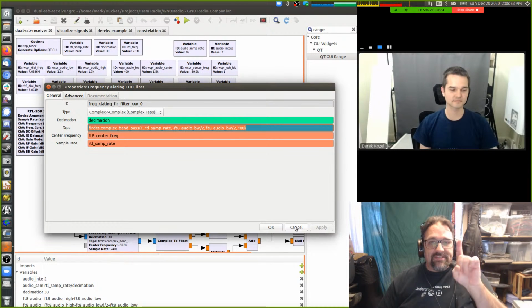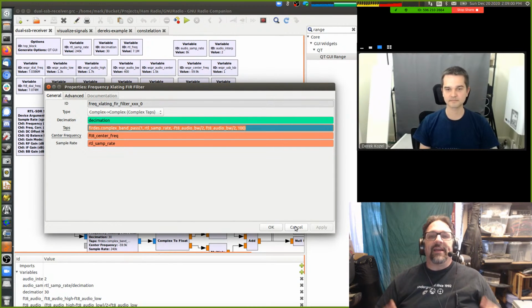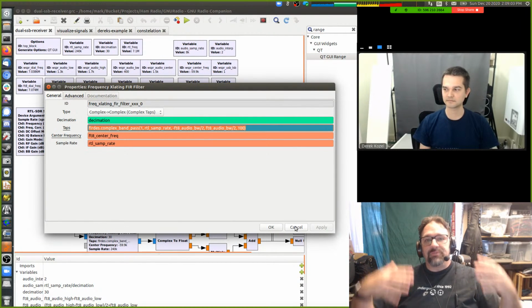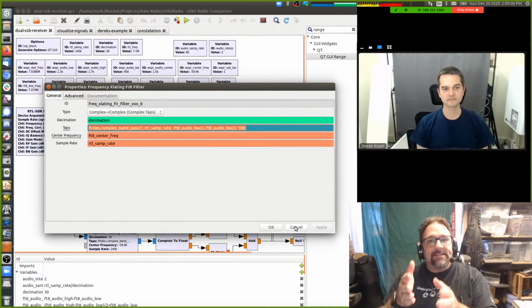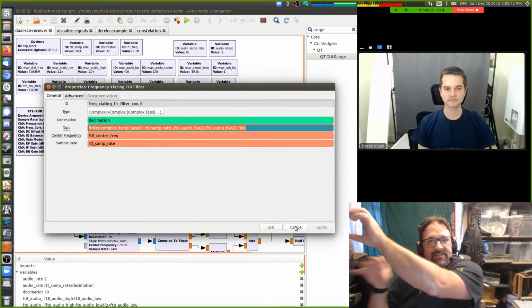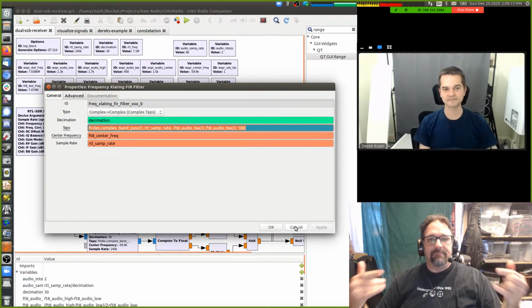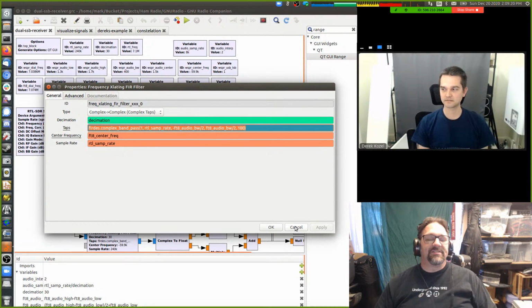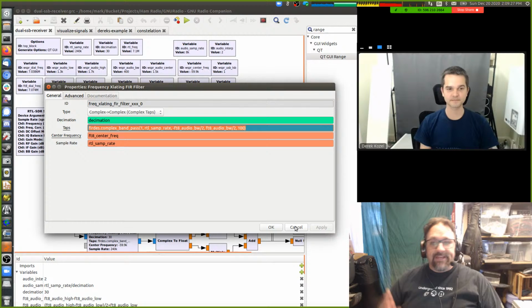So I'm now using a single instruction cycle to operate on 8 different values, 4 different multiplications. Again, it's a way of optimizing things when you've got a whole lot of multiplications that you need to do, and each one of those multiplications is independent. This value times this value, this times this. You don't need to do those sequentially. And so being able to do all of those in parallel in a single instruction really optimizes things. That's all because of FIR filters and that kind of thing. Yeah. So anyway.